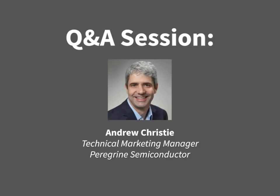This next question is definitely related to the previous one. Why does the line of sight case have a higher delay spread than the non-line of sight case? We discussed this also a little bit during the presentation. The reason for this is an error in the pointing between the source and the receiver. If there's an error in the pointing between the transmitter and the receiver, then the direct path signal will not be received and will end up reflecting off a faraway surface and then coming back. That's what creates the larger delay spread.